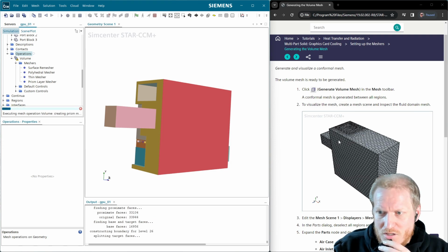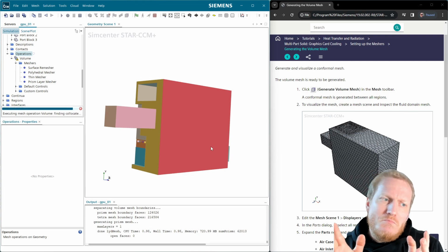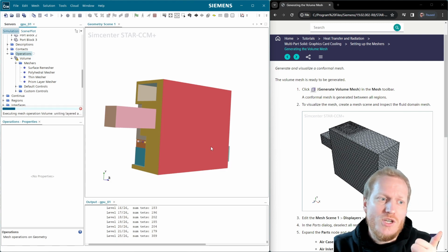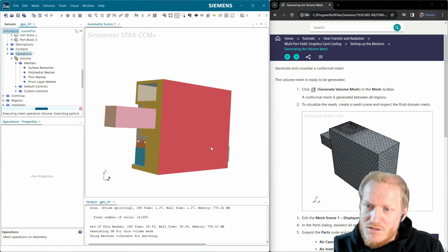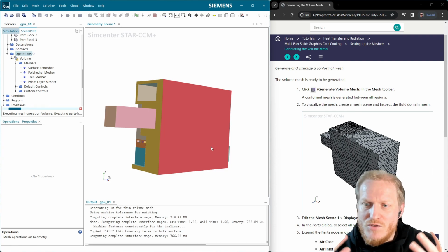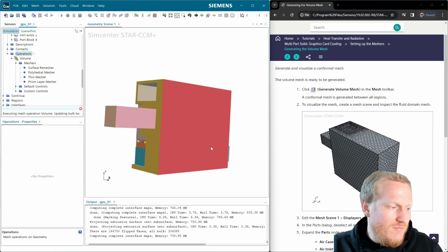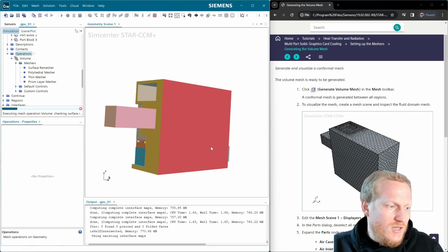Thing is that just didn't work is the individual surface mesh on every part. I thought it might be clever to let each processor core mesh a different part. That's why I opted for concurrent meshing and mesh per part. But turns out it didn't work, because sometimes then you have to sew these meshes together and errors can come up there.